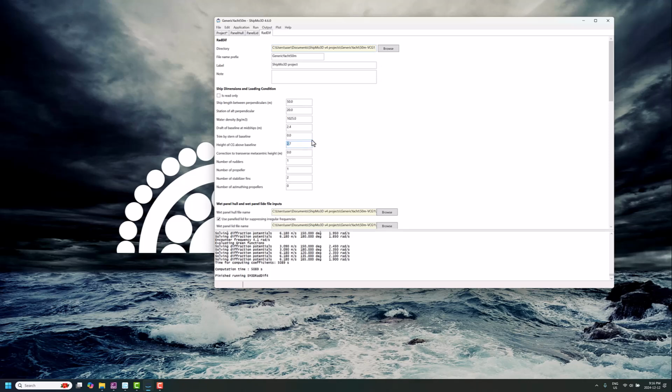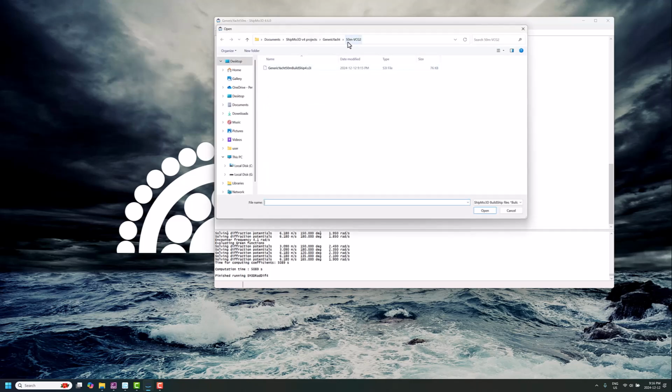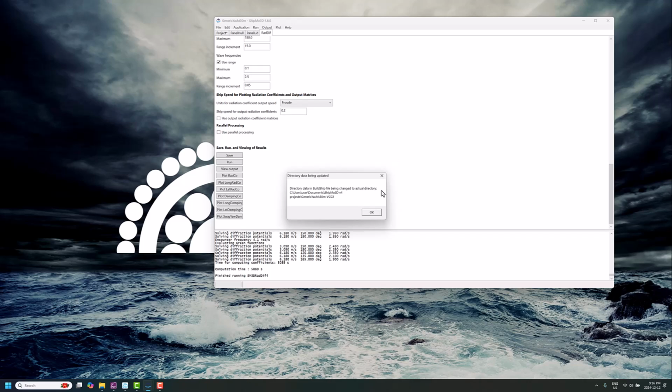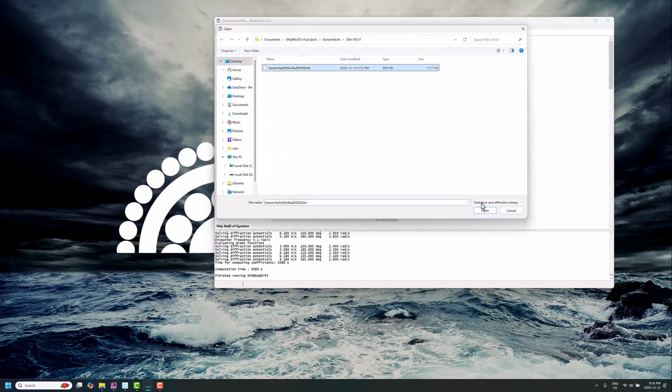This is with the lower VCG, and we will go through and do the same thing. So we'll go to build ship. Now see, this one has saved our old file location to VCG2, so you've got to be really careful. You switch over to VCG1 here. And remember, this one's got to also go down. We're doing the lower VCG for VCG1 here, 10% lower.